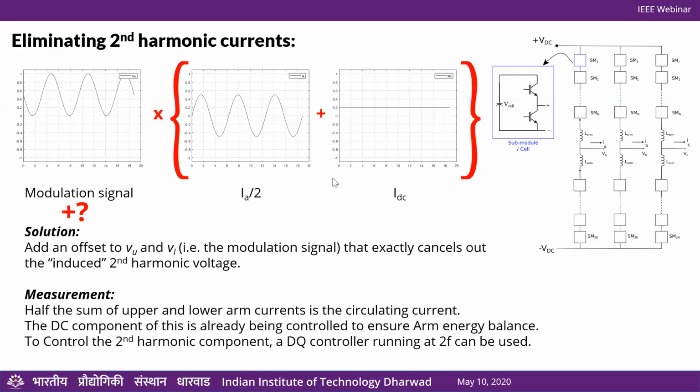Okay, so the next question is arm inductance. How is arm inductance calculated? Roughly speaking, arm inductance is calculated to act as a filter. The first reference that I have provided has some discussion of this arm inductor design, and there's a lot of involved process in figuring out what your C and L should be, the passives design, and it's more to do with system level considerations than purely electrical considerations.